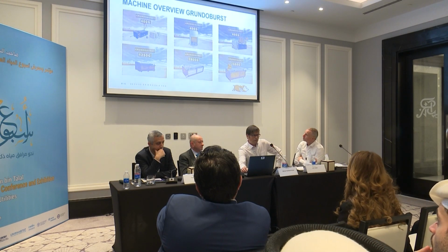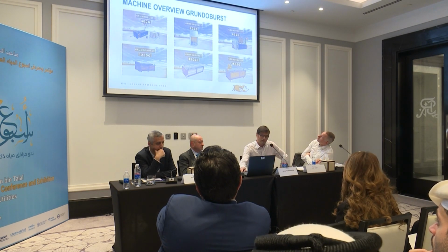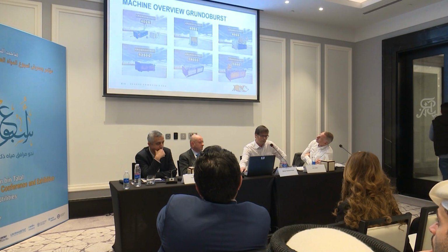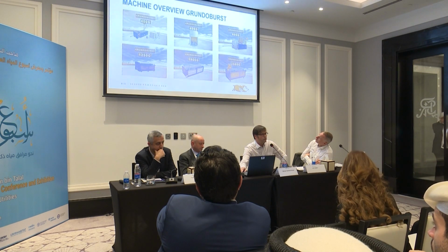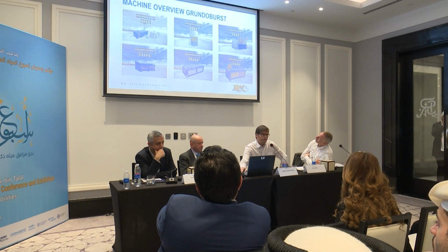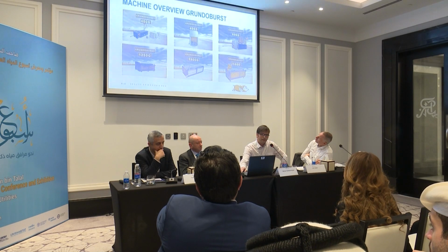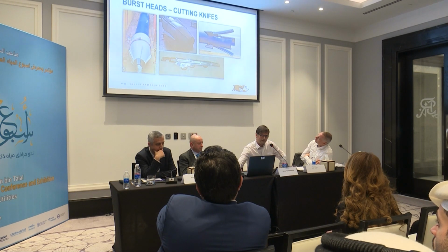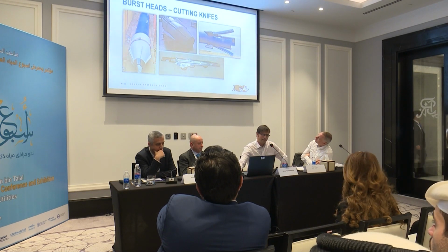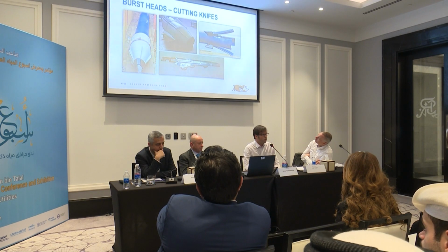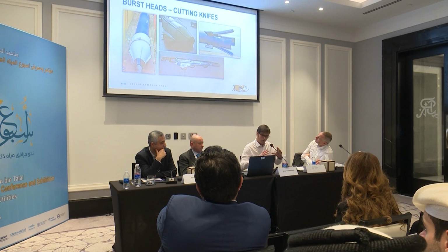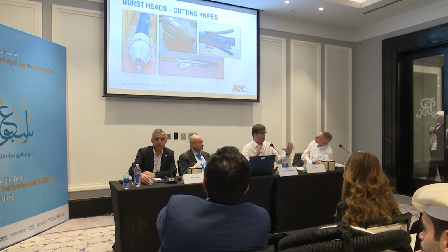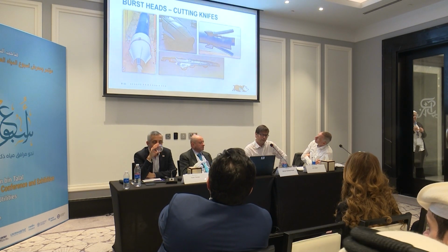Our range is from 20 ton to 250 ton pulling forces that allows you to pipe burst anything from 2-inch to 40-inch, so from 50 mil to 1 meter in diameter. And the key to the application is that we install a brand new product pipe of smaller, similar or identical, or indeed larger diameter into the existing pipe.